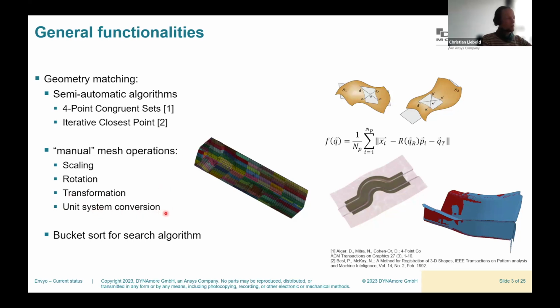If you come from different simulation disciplines, for example, short fiber reinforced modeling, or you move onto a crash model for a short time impact situation, there's usually a need to change the unit system. So we do have some predefined unit systems implemented, which allow you to convert from one system type to another. And that usually includes the scaling of the model, sometimes changing the values of the stress, the magnitude of the stress values.